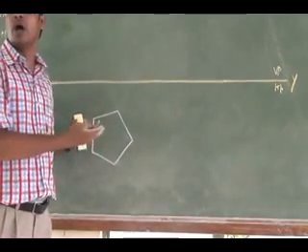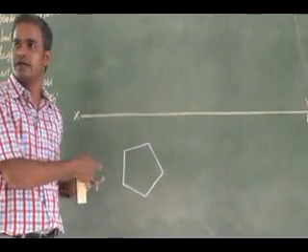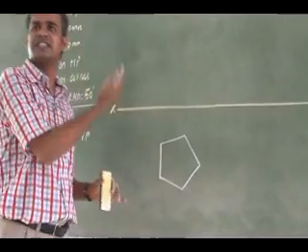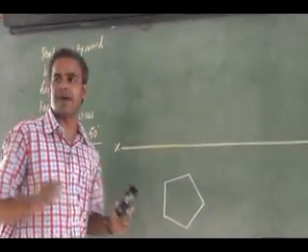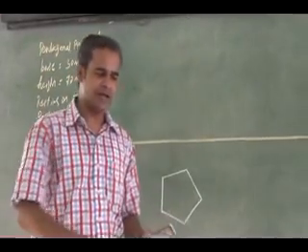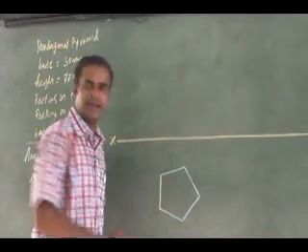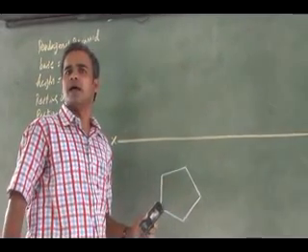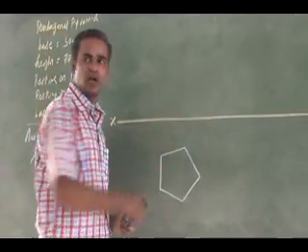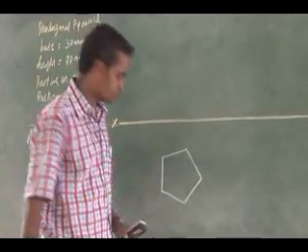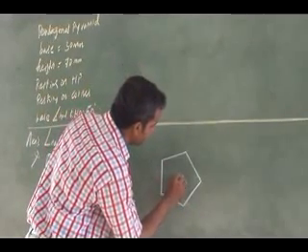In the extremes, I have a corner and an edge. Even if it is resting with an edge or resting with a corner, you can draw it in this orientation. Now it is a pyramid. Since it is a pyramid, I can see the side edges also. You mark the center of the pentagon, mark the apex, and show the slant edges. Mark the center.